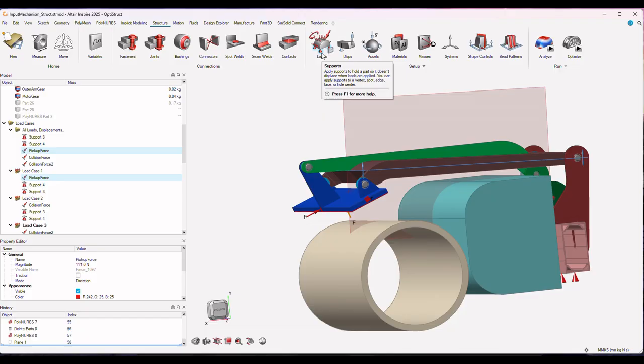While all these analyses are in the same program, motion analysis is a rigid body dynamics type solution, and it's a totally different analysis solution, and some of the constructs for that solution set are different. The structural is a deformable body, and the boundary conditions are the way you hold parts.